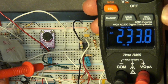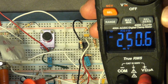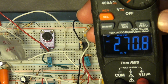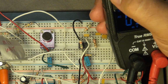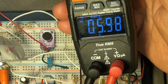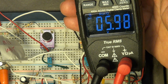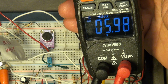Okay, so let's just touch the probe of the voltmeter to pin 6, which is also the oscilloscope probe. Oh, it's on AC. Okay, there we go, DC. And 5.98. 5.98, that's pretty close to 6. So, yes, it works. At least that part of it does.